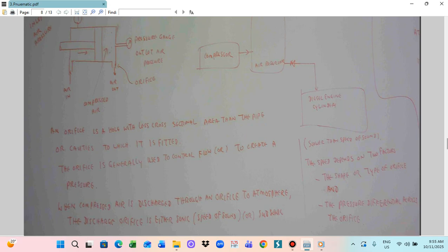This is the aircraft, and this is the tire. The aircraft tire holds very compressed air. You can see that the aircraft tire is a very small size, but its inside pressure is very high because of the physics. All the aircraft weight is carried by this tire, so its pressure and temperature are very high. So before you remove the aircraft tire, the important thing is that you gradually reduce the inside pressure.